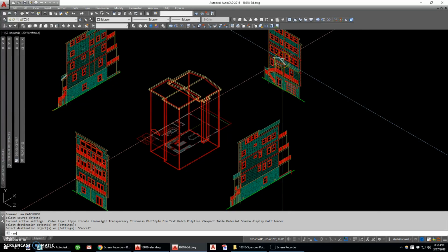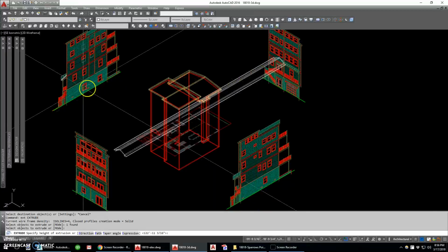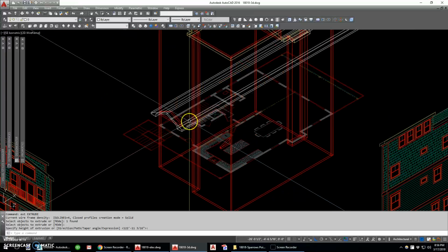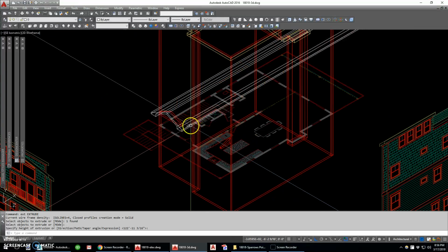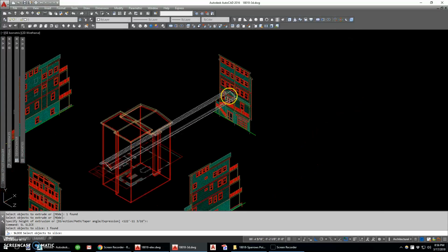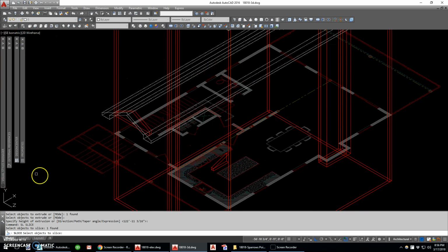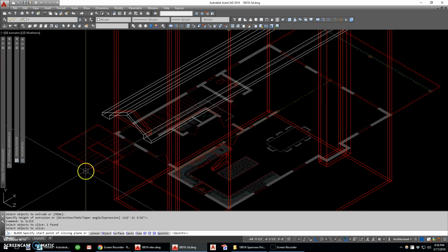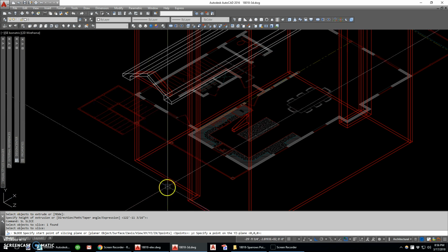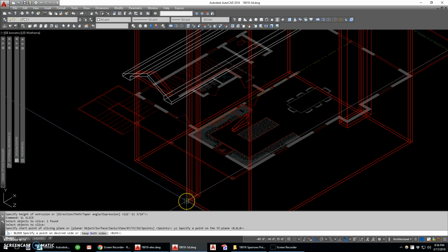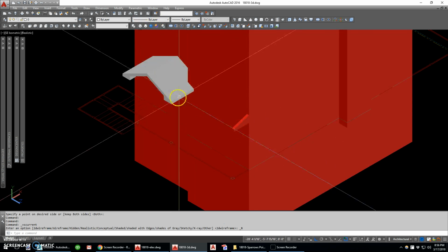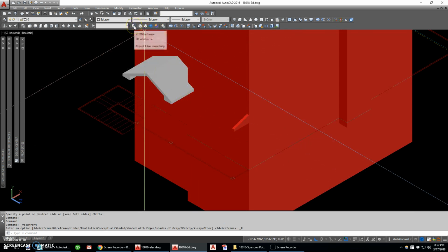Next, I think I'll start with the bigger part of the roof, so I'm going to extrude this roof out. Again, use the elevation as a reference to the distance. And for now, I'm going to slice this roof. You can see that roof intersects both roofs, but I want it going all the way back to the furthest roof. Now my UCS is on the side right now, but I can still go ahead and slice. I just have to be conscious and say I'm going to slice this time on my XY axis at the front of the wall and keep this half. So again, now this looks correct. I like the geometry not to intersect on the major items.